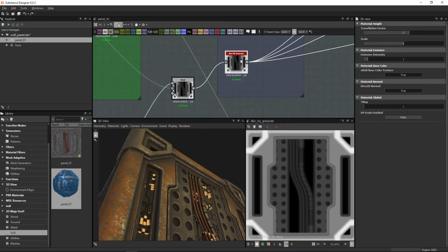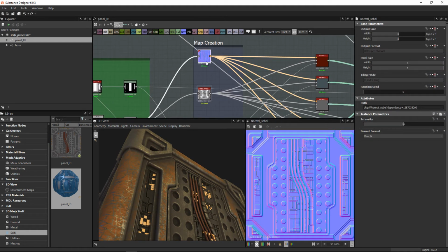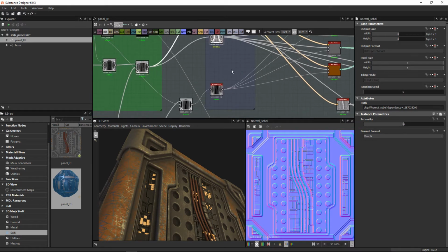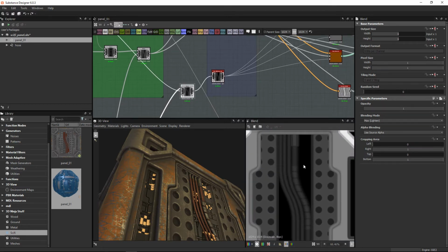So the idea, and I've talked about this a lot, is that the normal map is going to give you all your high frequency detail. And the other part of it here is that we're going to use the height for the displacement part. And in that, I don't want really fine-tuned high frequency detail in that height, because number one, you'd have to crank that tessellation up super high to retain that, and number two, it's just going to be real noisy. So what I do is I take my height, and you'll notice that this particular height is minus those panels in the background, because they're small detail shapes, that's the perfect type of shape for the normal map.